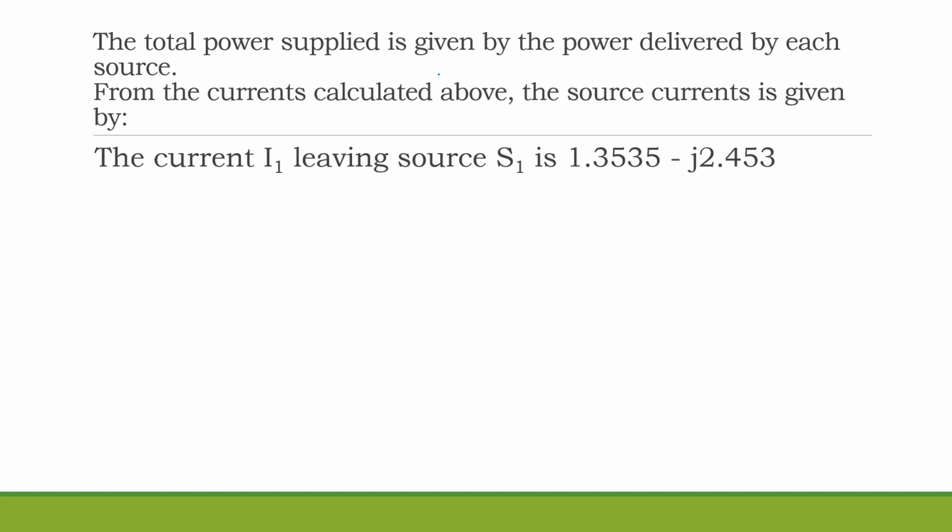Remember the current through the 20 was moving from node 1 towards the source because we had V1 minus V source, okay? So now we're looking at the current leaving the source, so it will be the negative of what you had calculated. So repeat that, please. It will be the negative.